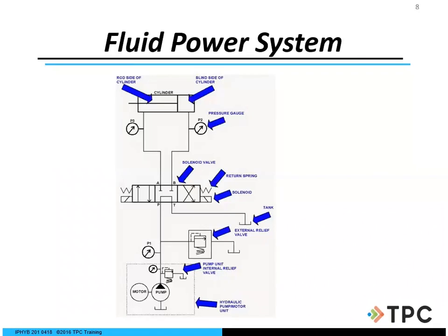Here we have the tank over here again. So a hydraulic pump motor unit. So when you see a line like this right here, that means it is an HPU unit, hydraulic power unit. And so everything is connected together, just like we saw on that last slide. And here is our mechanical coupling, or linkage between the motor and the pump. Very, very important. Over here is a little pressure gauge. We can see what pressure is coming through our lines and a pressure relief valve and so forth. And then we have another pressure gauge over here, external relief valve.